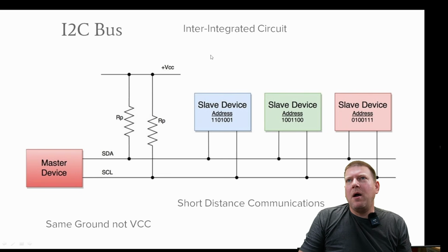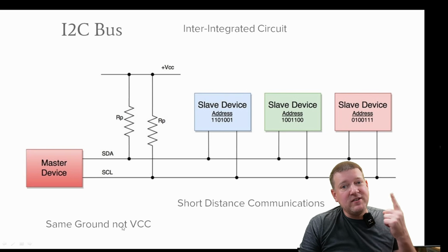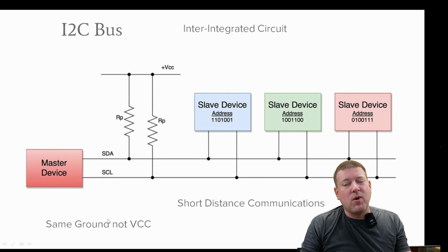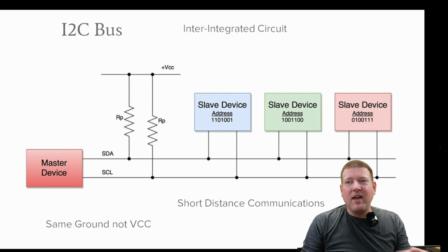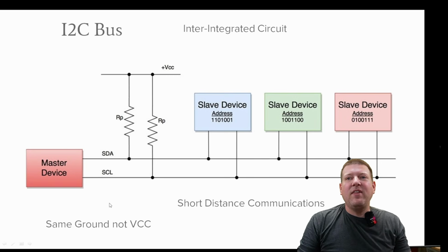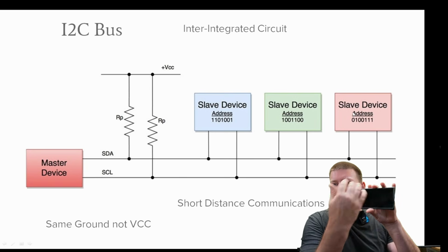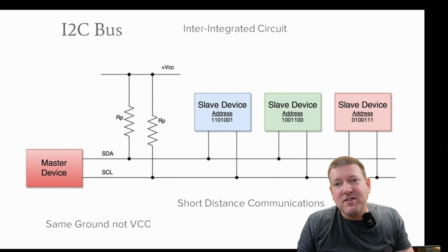So the other thing about this I squared C is we have a data line, we have a clock line, we have a VCC pin, so it does have some sort of voltage that's required for this one, and then there's ground. And I already said earlier that all these devices right here, they have to share the same ground, which fortunately, if you're talking about in the body of a cell phone or whatnot, you're all going to have the same negative plane.